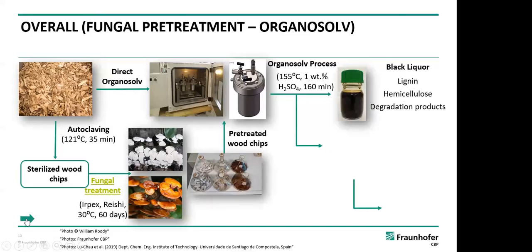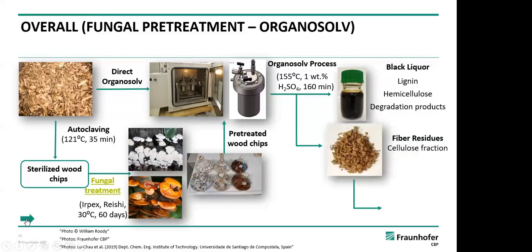And we will get lignin by adding water to the black liquor. Lignin precipitates, then is filtered. We got lignin washed with water to remove the ethanol and residual sugars, and dried at 50 degrees under vacuum. And for the liquid phase, we evaporate and recover ethanol from it, so we can use it in another process. And we evaporate most of the water to get the xylose and some degradation compounds.